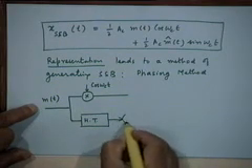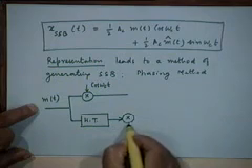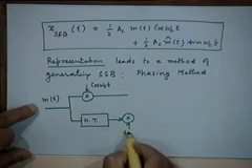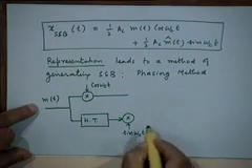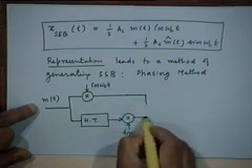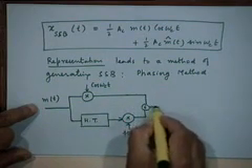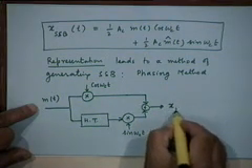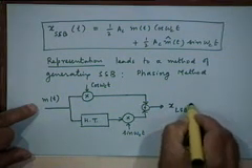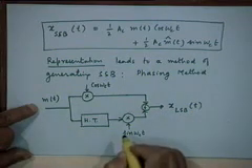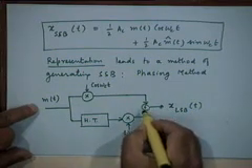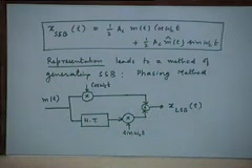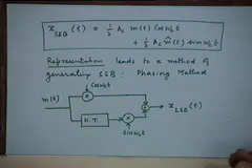And that's followed by a second product modulator in which the carrier is sine omega ct, and you simply add up these two to produce your lower sideband signal, right? If you subtract one from the other, you will get the upper sideband signal. So it looks very neat and very simple, right?